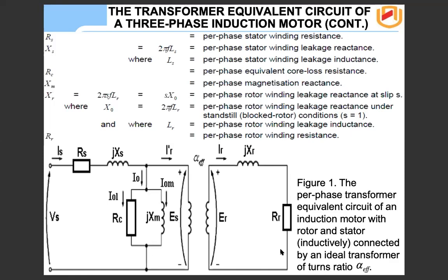In this case, we have not yet talked about the mechanical power that goes to the shaft. We are basically looking at the losses in the rotor coils. So here we have a rotor reactance and then rotor resistance. This is the rotor EMF, the EMF induced in the rotor coils, and this is the stator EMF, the EMF induced in the stator coil. So far, there's nothing new.